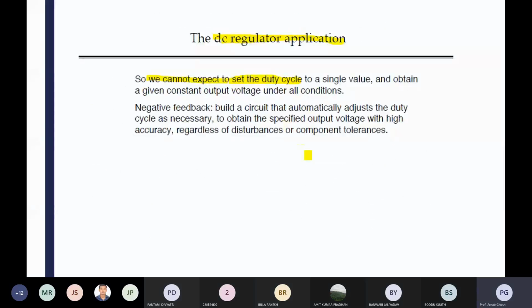So you are changing the control signal. If the value of your control signal changes, the PWM width changes. How does the value of the control signal change? If suddenly your output voltage goes high, your error will be less. So your control signal will be less, and if your control signal is less, the duty ratio will be less, meaning the switch on time period will also be less. The converter works for very few moments, the switch off condition will be high, and again it will balance the voltage.